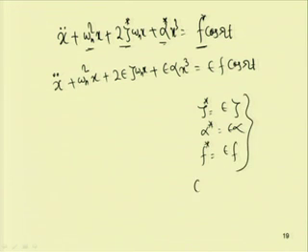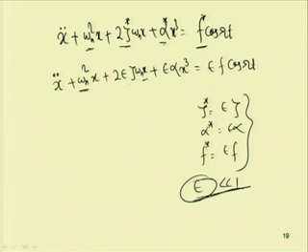Here, epsilon is a bookkeeping parameter which is much less than 1. This bookkeeping parameter is used to make the coefficient of the nonlinear term similar to that of the linear term. For example, in this case the order of epsilon zeta should be near to that of omega n square, and the order of alpha should be of the same order as that of omega n square. So, after ordering this equation,